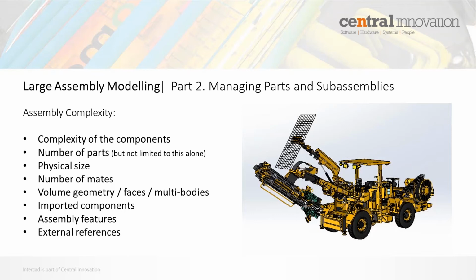100 parts in an assembly is actually quicker to load and rebuild than one single part with 100 bodies in it. That might be a little bit surprising, but there you go. Imported components, obviously I've just sort of discussed that.